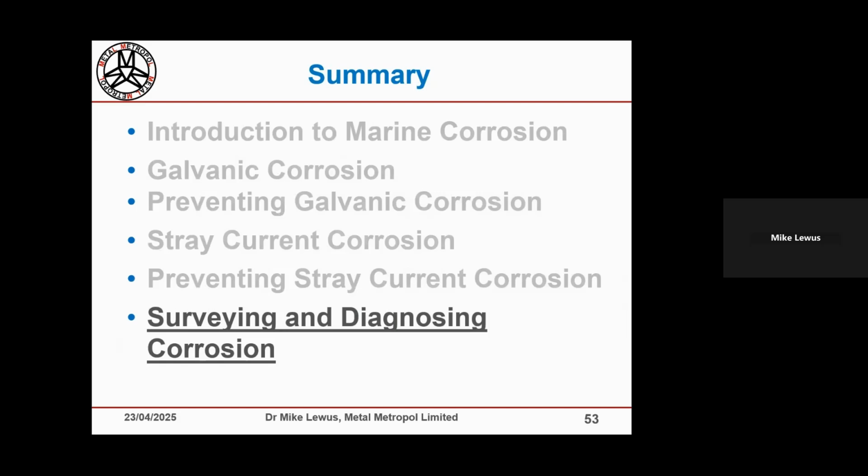And the other thing, I've never seen one, but I know some people do have polarity indicators. If you're flitting from marina to marina, I don't know of many instances of this, but I've heard people say they came to a new marina, plugged in their power, and a polarity indicator showed that the wiring on the dockside was the wrong way around.